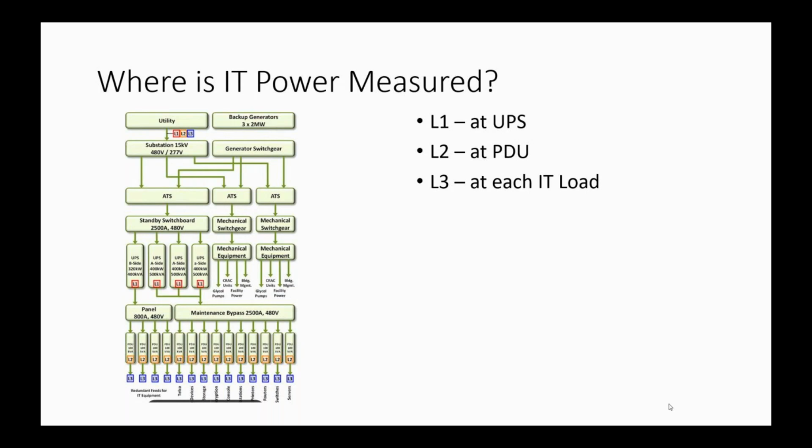You could measure that at the power distribution unit going into each of the racks or rows in your data center, or you could measure them at the IT load itself. As you can see, you could measure it any number of ways, but where you measure makes a difference on what PUE you come up with.